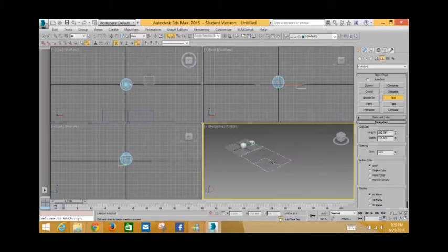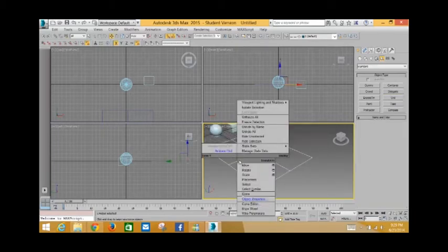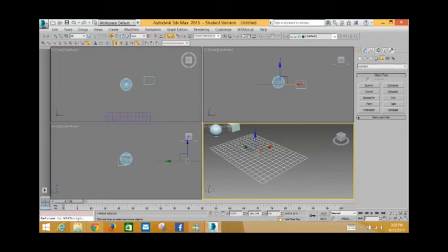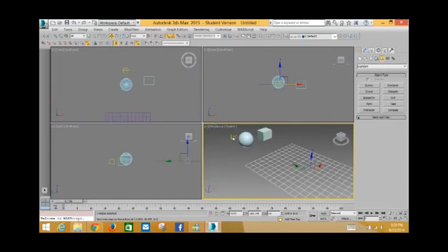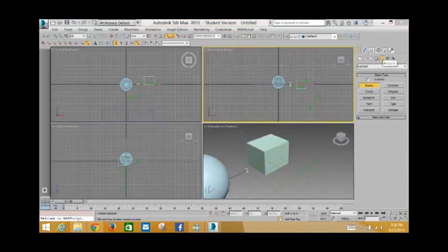I've got what I want there, so I right click on that and activate grid. And all of a sudden that becomes my new construction grid. It sort of mutes down the home grid, because this is the grid I really want to see. This is the one I'm using to construct things off of. So there's a little trick there.